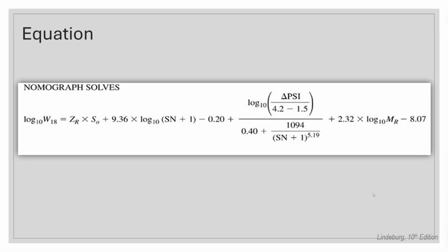So when I start looking at this equation, it looks like you just plug in numbers and you get an answer, and that answer is log base 10 of our ESALs, but we already know ESALs. That's not the goal. The goal is to figure out what is my structural number. And structural number is tied up here at the beginning section of the equation, and then also at the bottom of this really messy part of the equation. So solving this for structural number is not that easy.